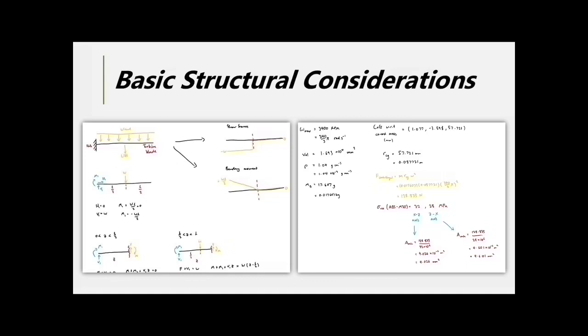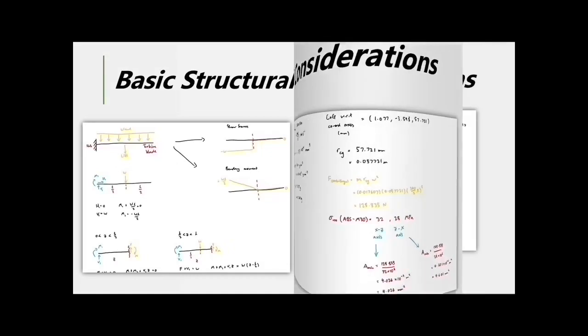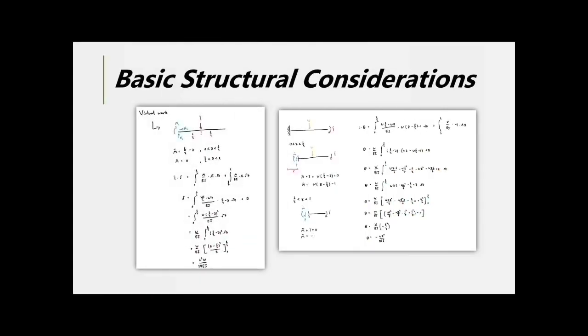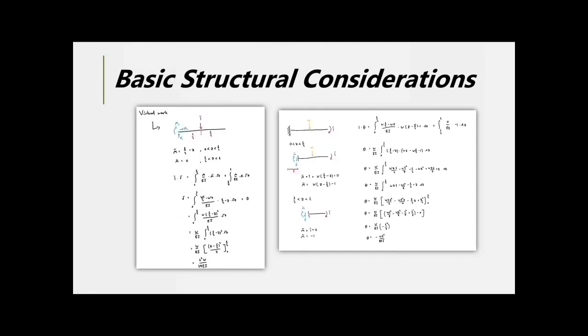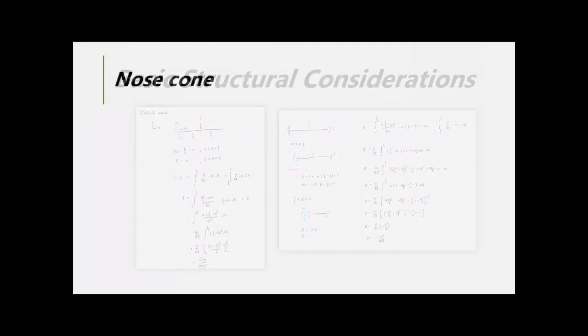However, our calculations show that the current design is strong enough to withstand the centrifugal forces and associated stresses of operation. We also took into consideration the bending moments and shear forces to be experienced whilst in operation. The analysis showed that they would be maximum near the root of the blade and 0 at the tips, which prompted our design of a high to low chord length from the root outwards. We also utilised the virtual work method to estimate deflections. Note that the turbine blades were modelled as simple cantilever beams, which provided a suitable approximation for this purpose.